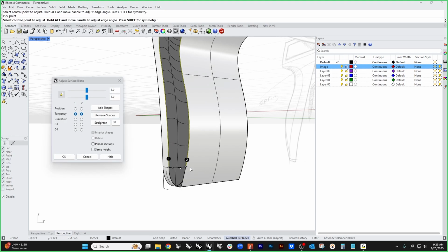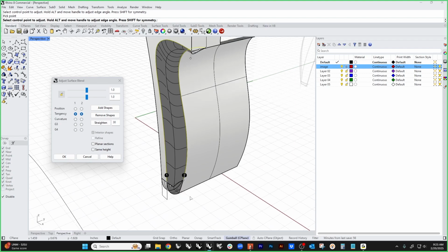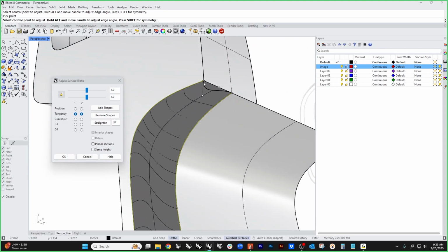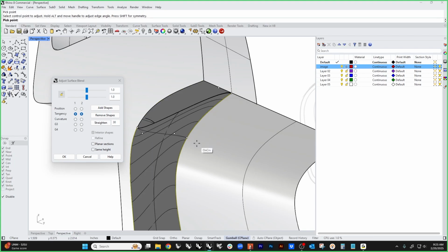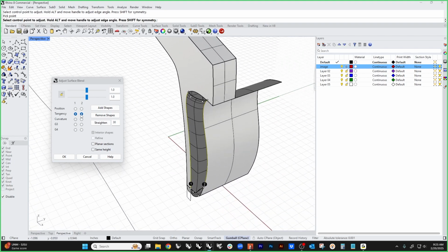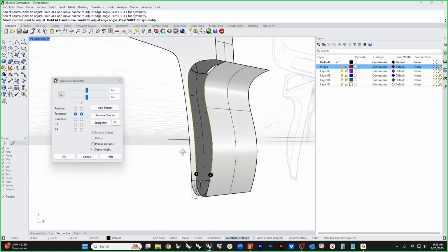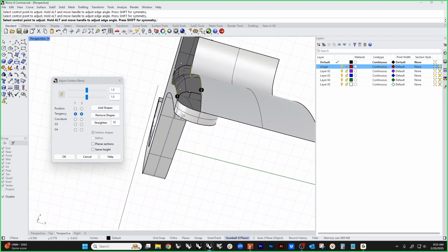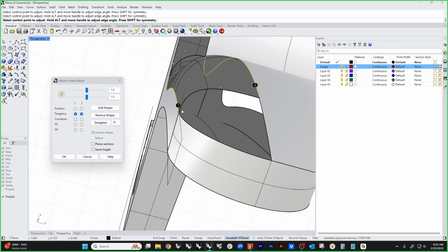If I move the start endpoint up to here, it's going to give me a little different result. And if I move the start endpoint someplace comfortable down in here, and then I fiddle these settings, you'll see that this surface starts to behave. Now, what do you notice about this? This has 2 points in this direction, which means that this point, and whatever is this next point in this surface down here are lined up.